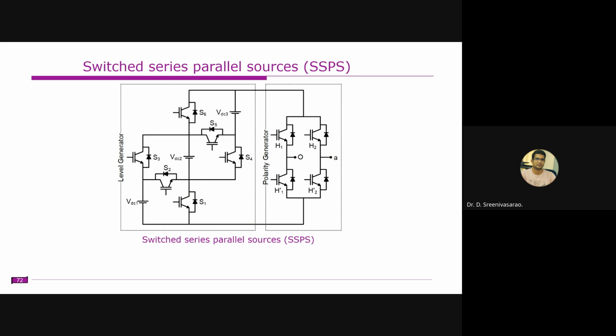So this is one of the advantages. Another thing is that we normally have a single DC source here, so we can replace these with capacitors. Now you have only one DC source. To charge the capacitors, if you turn on switches S1 and S5, all the capacitor negative plates are connected. Similarly, if you turn on S3 and S6, the positive plates of the capacitors are connected. So the equivalent circuit in this case is like this. Now all the capacitors are charged to VDC, VDC, VDC.